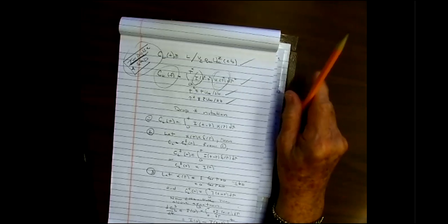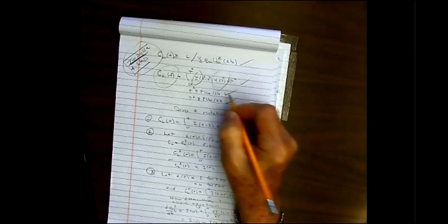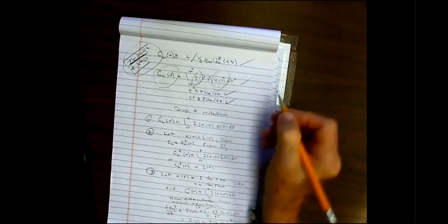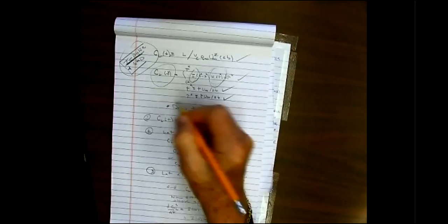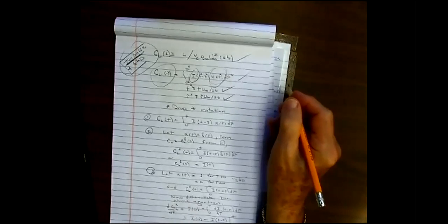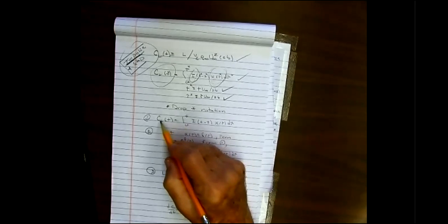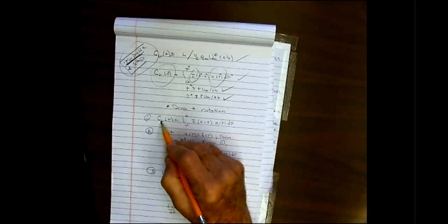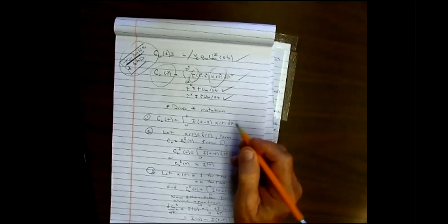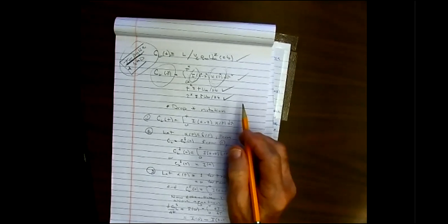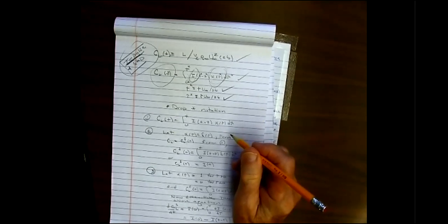Okay, I know some of you are running CFD codes, so you might want to try this with your favorite CFD code. It will work. Okay, so now next thing we're going to do is we're going to drop the star notation because it's cumbersome, right? So now we're dealing just with everything non-dimensionalized. This is a non-dimensionalized lift coefficient. Alpha is a non-dimensionalized angle of attack, and we're generally a downwash divided by U infinity. Tau and t are non-dimensional times.